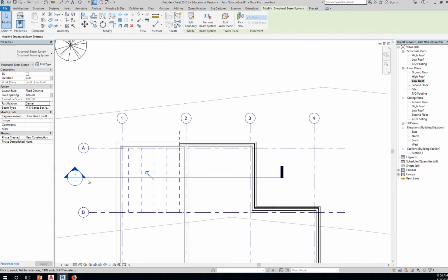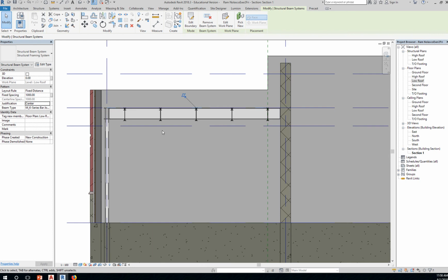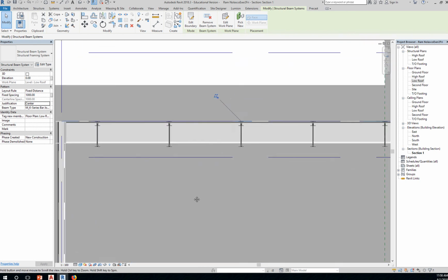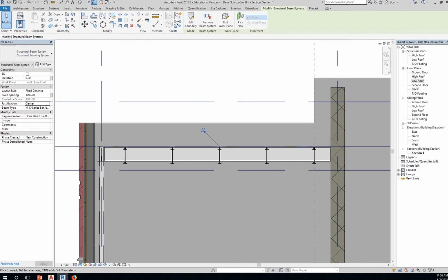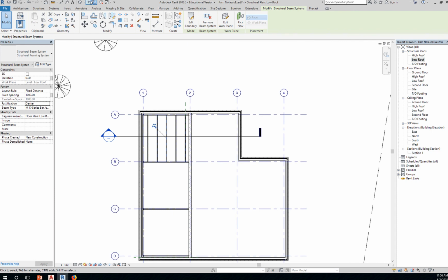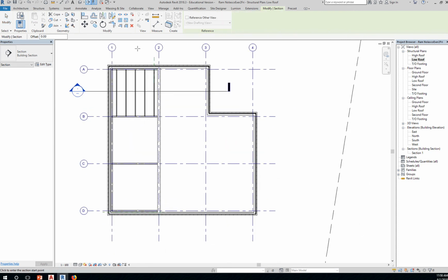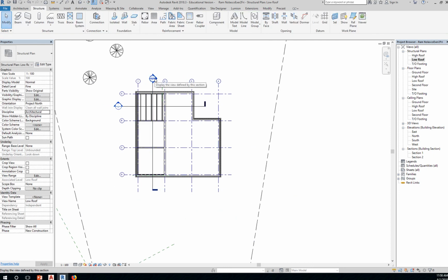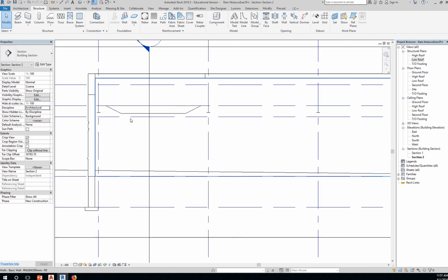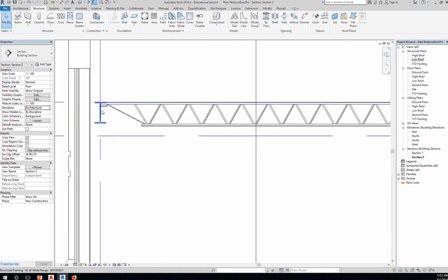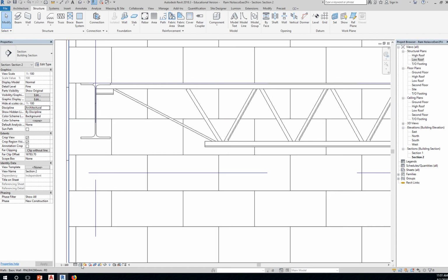Okay. Again, always go to your section view. Okay, and in this case, you might want to create a section view going the other way. So let's go here. Okay, click outside, double click on the section head. There you go, and change this to a fine detail level, shaded.